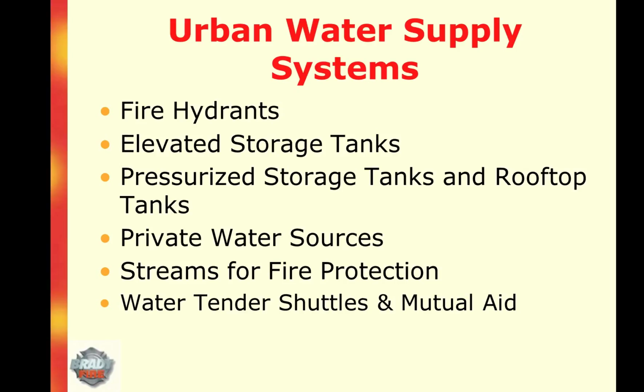Rooftop tanks are typically installed inside the building, or they may be mounted at rooftop to provide 15 psi pressure at the topmost sprinkler head. Water sources on private property may be required for public protection, and legal agreements should be established. The fire department needs legal right of entry, although the FD can have the right to enter properties that are on fire. The fire inspector, as water supply officer, should establish the formal agreements with any private water source that may be required for community fire protection.